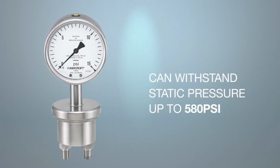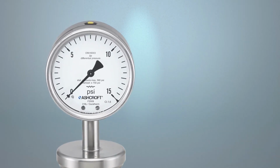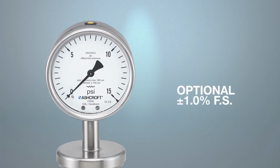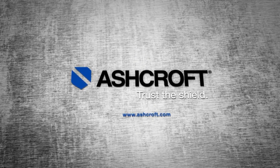The all-welded F5509 open front and F6509 solid front differential pressure gauges can withstand static pressures up to 580 psi, eliminating the risk of catastrophic failure due to excessive pressure. And it can deliver differential pressure readings in accuracies of plus or minus 1.6 or 1% of full span. We will be happy to help you find the best instrument for your application.